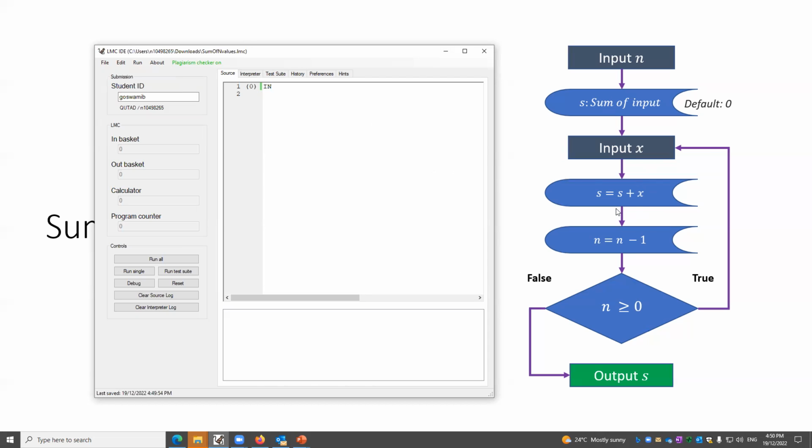What happens is that the count goes down to 0, so 0 is included. If we want to take 5 values, we should count 0, 1, 2, 3, 4. So in that case, we may have to reduce one value because it goes till 0. That's why for this logical operation, I want to subtract. But I don't have the values stored anywhere, so first I will write the HLT, and then I will write the data section.